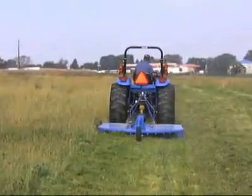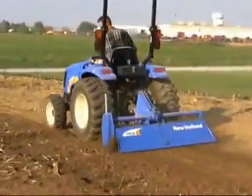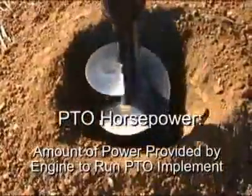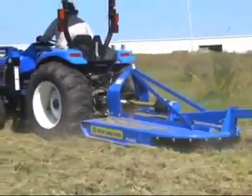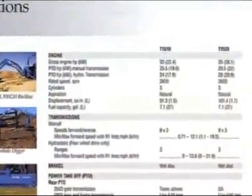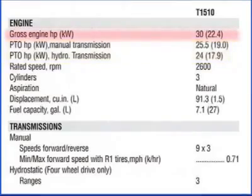So, if the PTO powers the tools that do the work, you should be interested in how much PTO horsepower your tractor creates. PTO horsepower measures the amount of power provided by the engine to run a PTO implement. Now, it's not possible to deliver 100% of the engine's horsepower to the PTO because the engine loses some power during the power transfer or to the other components of the tractor, like the transmission, alternator, or power steering pump. Therefore, a tractor's PTO power is typically 10 to 20% less than the gross engine horsepower.